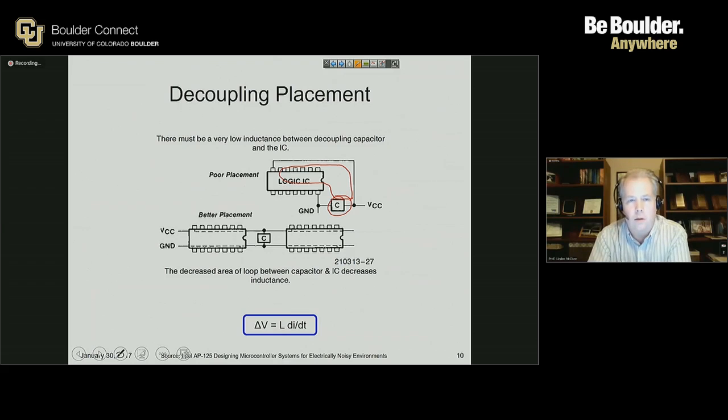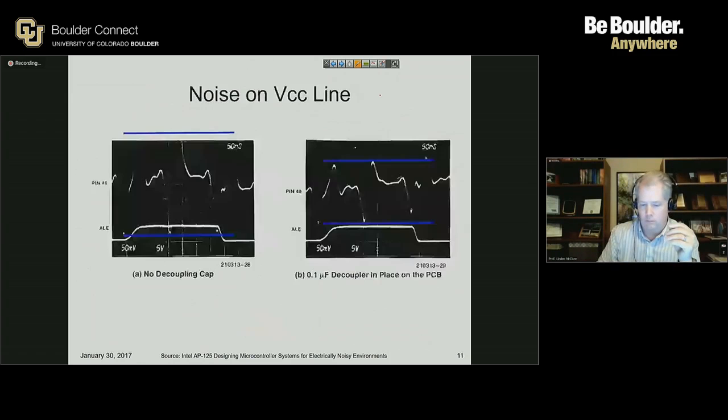So when you're designing your circuit for the class this semester or for any embedded hardware design that you want to do after this class, not only should you reserve space for decoupling capacitors, but you also want to make sure that as you place those components on the board, you're thinking through, okay, what chips does this capacitor need to help? And place the capacitor close to those chips.